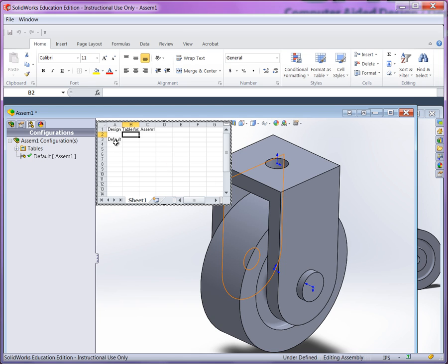Okay, again, along the rows here, we'll be able to create the different assembly configuration names. So why not go ahead and start with that. We'll do A, B, C, D. Let's make sure that says D, E, and F. Now, the parameter that we're tracking is the parameter of the configuration for each part.